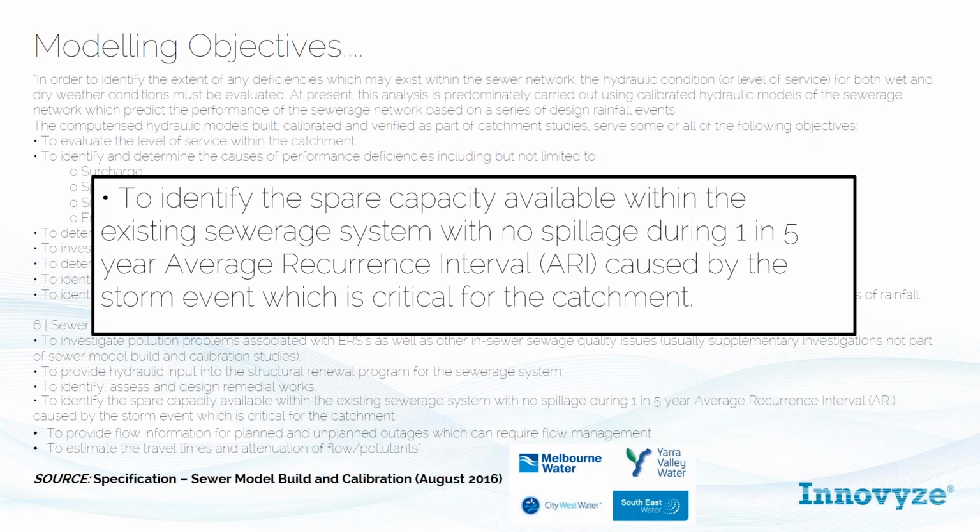So I guess Logan City Council did start with a 1-year ARI containment standard, and that was applied successfully in that Slacks Creek catchment, which I spoke about earlier. But we have some other catchments where it hasn't worked out as well and has resulted in pretty significant expenditure. So we're now moving to a bit more of what we call a risk and effects-based containment standard. So really starting to look at catchment-specific issues and risk to the community and community expectations again, and risk to the environment of particular overflows. So some locations the overflows might not have as high a risk, other overflows the risk might be higher.